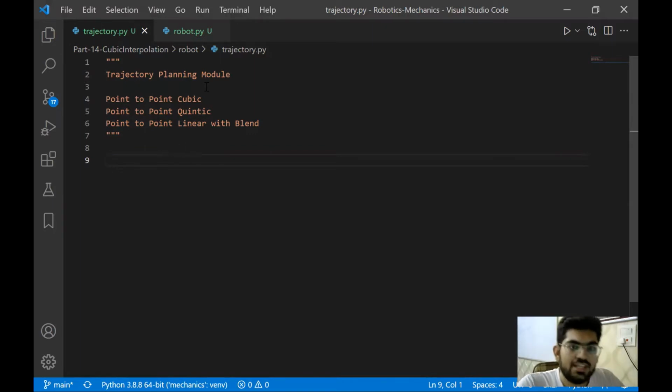All right, now trajectory planning actually comprises two subparts. Path planning and trajectory planning are slightly different if we define them differently. Path planning is selecting a path for a robot that the robot can follow. That's all right, there can be a path. But trajectory planning actually assigns a time-based schedule to that path.